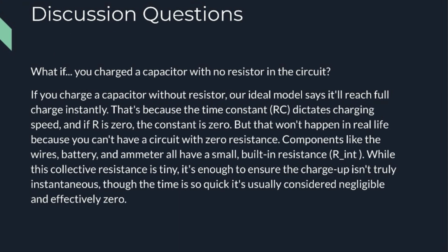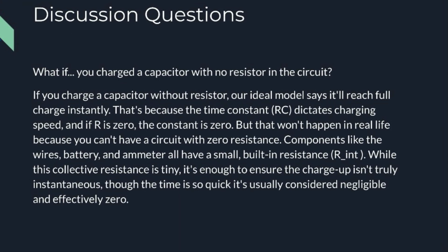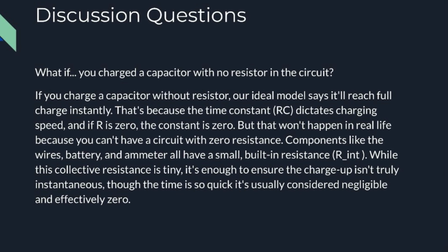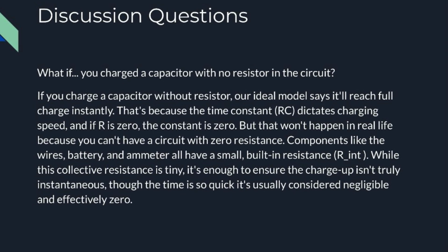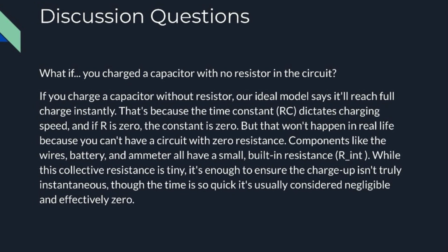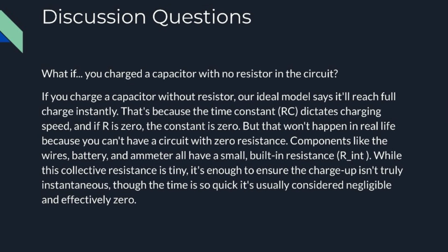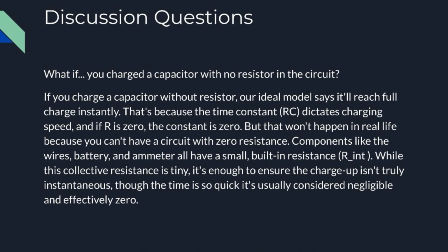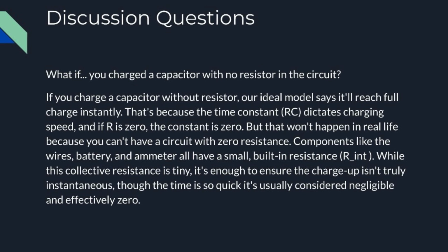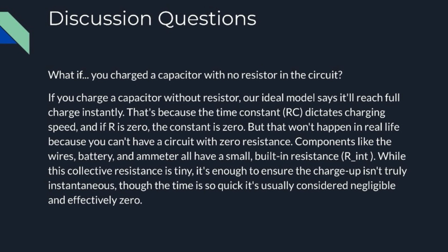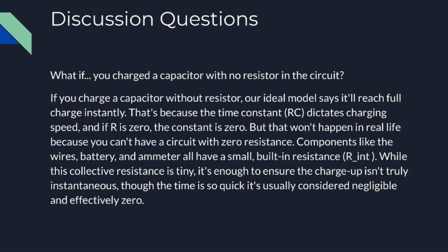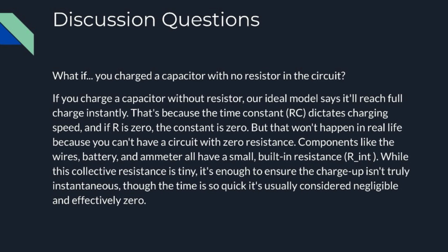Discussion question: what if you charge a capacitor with no resistor in the circuit? If you charge a capacitor without a resistor, our ideal model says that it'll reach full charge instantly. That's because the time constant RC dictates charging speed, and if R is 0, the constant is 0. But that won't happen in real life because you can't have a circuit with 0 resistance. You're always going to have just a little bit.